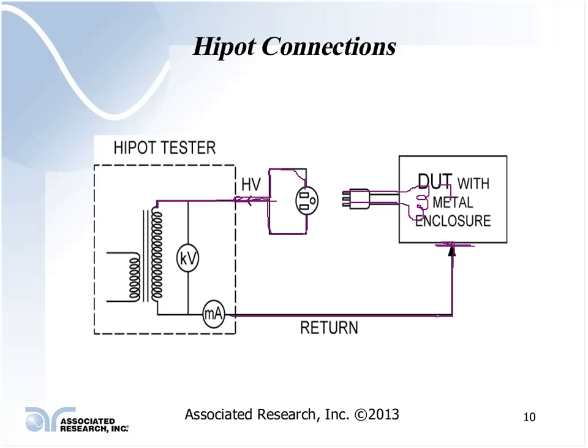If there's a capacitor, windings, an indicator light, whatever is within the product, the same potential is being applied to both sides of these components, and we're essentially testing the insulation between these components and the enclosure, both on the hot side and the neutral side of the line.